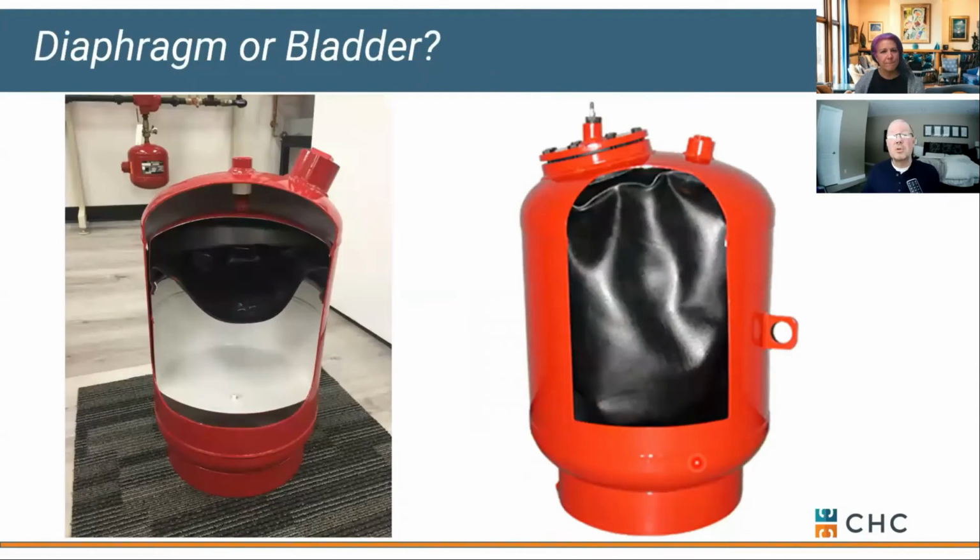Which one do you choose? Well, if you're chasing price, diaphragm all day long. It's definitely a cost-saving option. Just remember that if something goes wrong with this tank, you're going to have to isolate it. You're going to have to remove it from the mechanical room and bring in a replacement. There's no way to service it, okay?